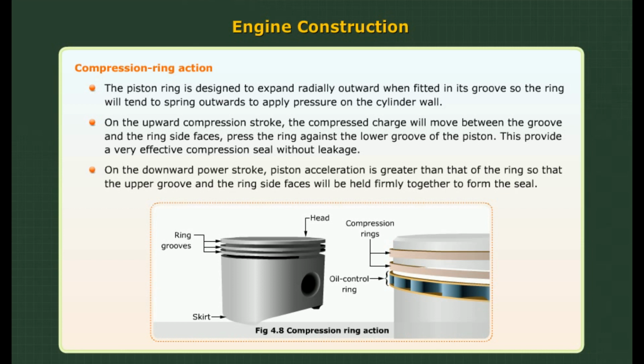On the downward power stroke, piston acceleration is greater than that of the ring, so that the upper groove and the ring side faces will be held firmly together to form the seal.